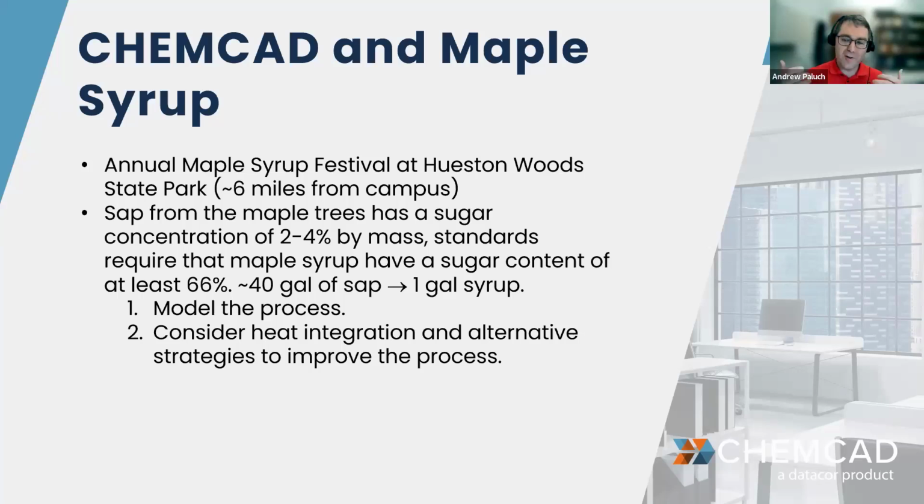And so we encourage the students to go out. It happens over the course of 2 weekends. And then when they return to campus, we have a fun exercise of, well, let's model this process, right? And this can be handled as early as students in the sophomore year, right? I can just do a simple mass and energy balance, and I could calculate, say, the required heat duty for this process. We model our evaporator essentially as a flash drum. We can perform a mass and energy balance on it and calculate the heat duty.